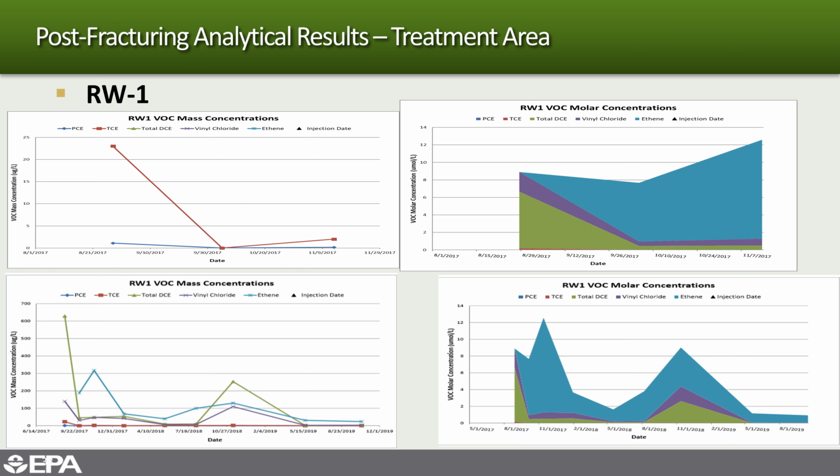5 micrograms per liter, for instance, for TCE is the maximum contaminant level, and oftentimes the number they're shooting for in groundwater cleanups. So here we have a big reduction, but we're starting to see a little bit of an uptick within a few months, possibly some continued diffusion happening in those newly fractured zones. So it's a double-edged sword in that we're immediately reducing contaminants, but we're also opening up some zones where we may get access to contaminants quicker than the diffusion rates, which they are typically limited by.